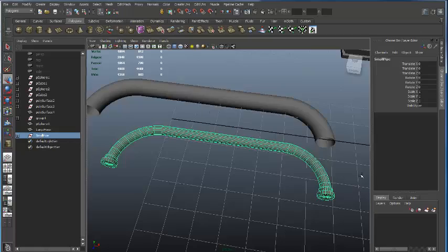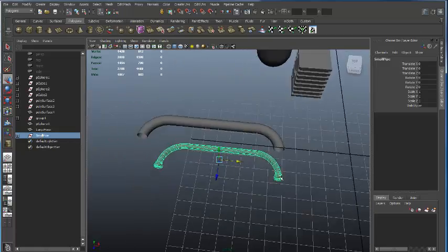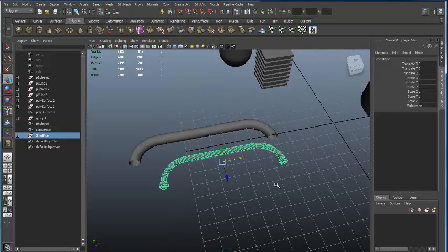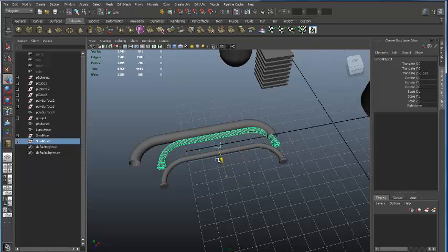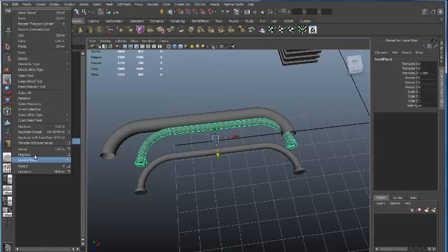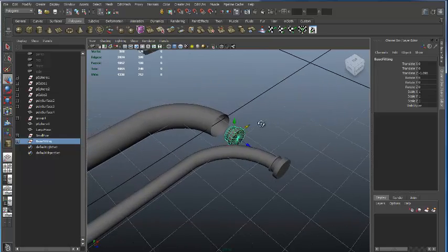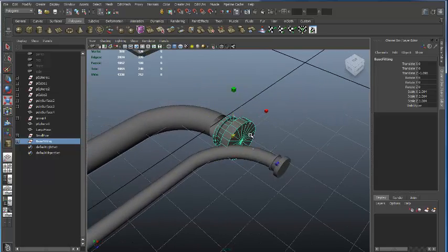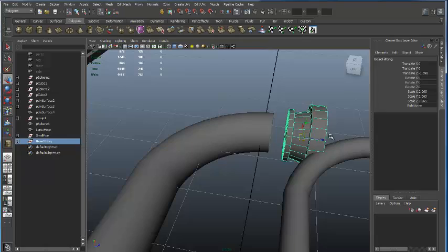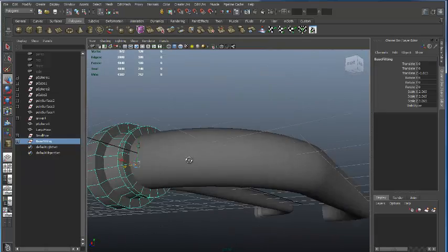Hit enter. So, in the center. The one thing though that I was going to do is I wanted to grab that piece, enlarge it and put it here, and I just forgot it and I grouped it. So to save myself time, I'm going to duplicate that object, move it over right here. Okay, go down under Edit. I'm going to tell it to ungroup real quick. I'm going to delete the parts of my model that I don't need. Take this particular pipe right here. I'm going to rescale it up and raise the size of it, come over and slip it right on the end of my other piece right there.